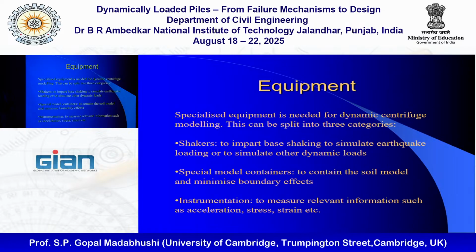And if I want to apply something like 0.25 G earthquake on it, I need to hit that with 25 tons in the lateral direction to model 0.25 G, which means that my shaker needs to be able to produce big force. And also it has to do it quickly, which means the power requirement is quite high.